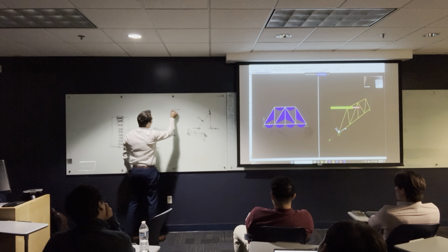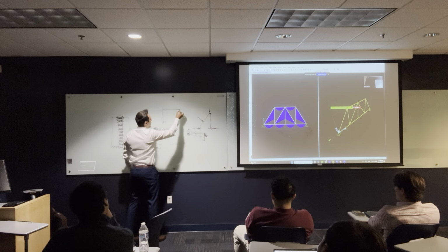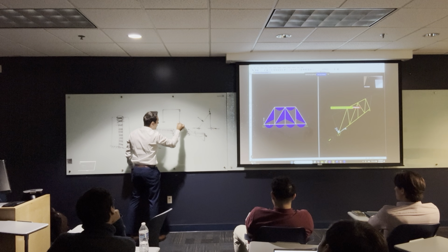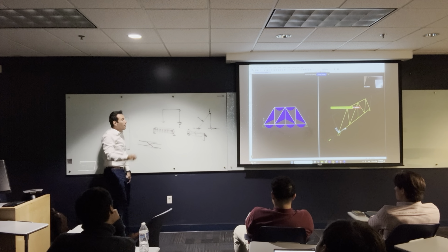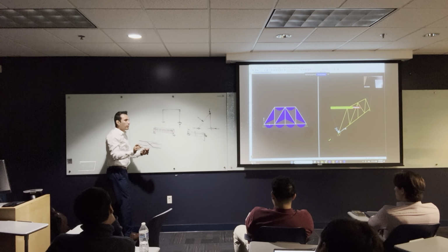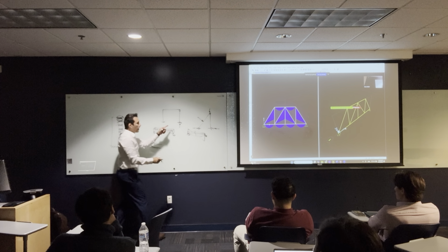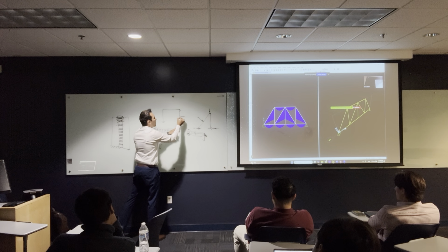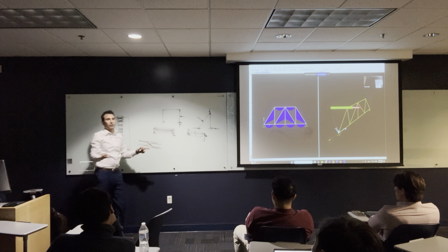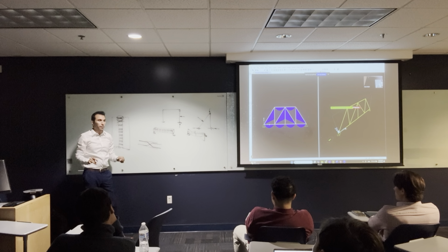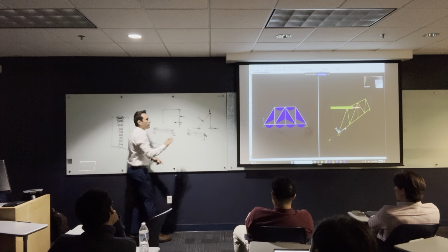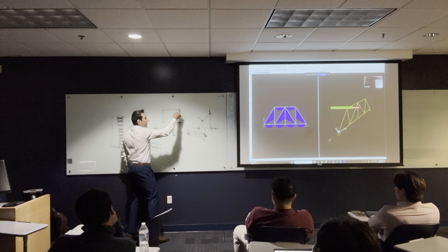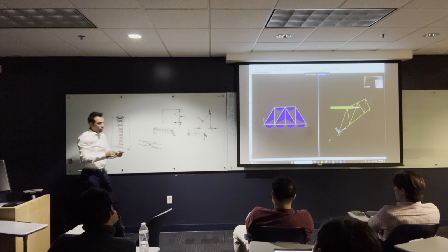And if you guys remember, we had something like this, a frame, and I told you there's something called a link member that only has one vertical reaction, something like this. Link member is a truss member. But if this link member has a load like this, that's not a link member anymore. That's a frame member. Why? Because right now you are gonna have a reaction that way, and this is gonna act like a frame, and it's gonna have a bending moment like this, so it's gonna be different.